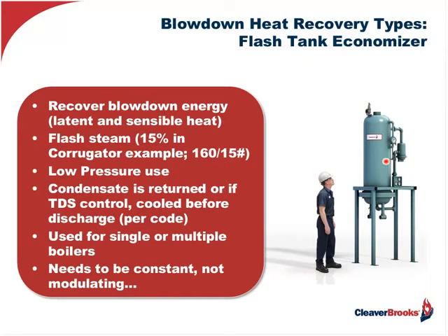Also, I want to call your attention to the fact that if you're going to be capturing continuous blowdown from your boiler, because you're trying to control the conductivity in that unit, that particular condensate cannot be used in the boiler itself. When you flash that off, anything coming from your total dissolved solids, you can flash off the steam and use that, but the condensate cannot go directly into the boiler. It could be used in a shell and tube heater to preheat feed water, but never directly into the boiler because of the contaminants within it.